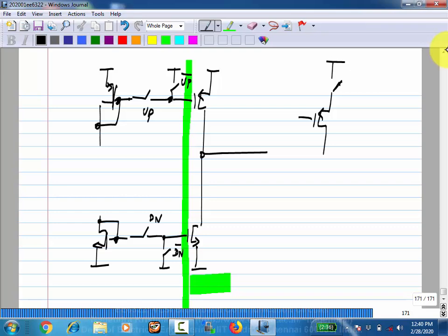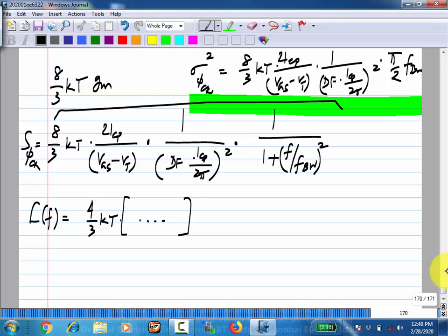Any questions about any of this stuff? The point is you can calculate it. Like I said, all of these things become more crucial when you don't have the forwarded clock, but with this also it is important. Okay. And the main thing that you see is that if you want to reduce the noise contribution here, you have to increase the charge pump current. Okay.